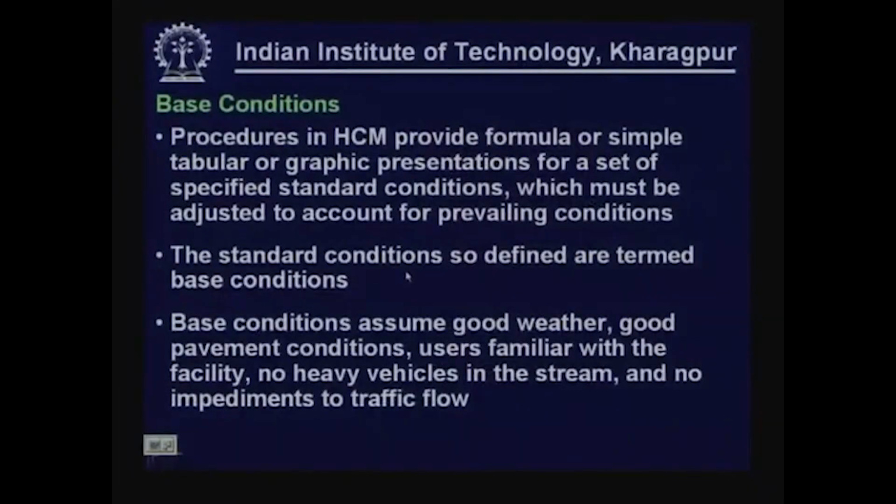The standard conditions that are used in HCM are termed base conditions. Base conditions assume good weather, good pavement conditions, that users are familiar with the facility, there are no heavy vehicles in the traffic stream, and there is no impediment to traffic flow. Through all this, the base condition or the ideal condition is defined.